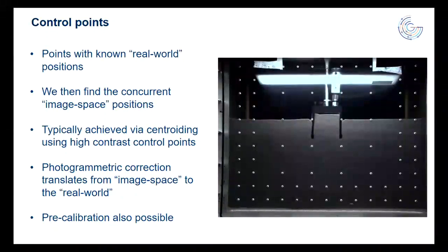Now, the downside of this is you can see that we include quite a significant part of the model here. We don't want to be taking measurements right in close to each of these markers, because we're going to get static parts of the displacement field. The markers don't move, and so effectively what you get is decorrelation as a consequence of that.